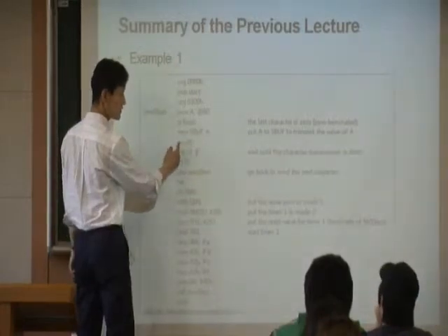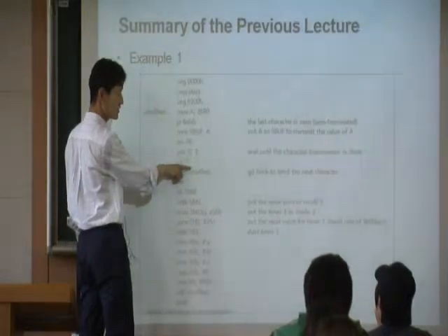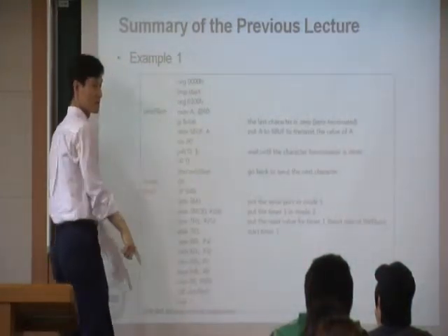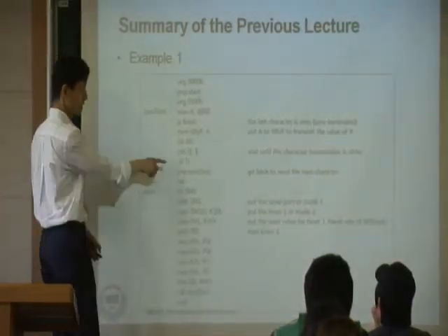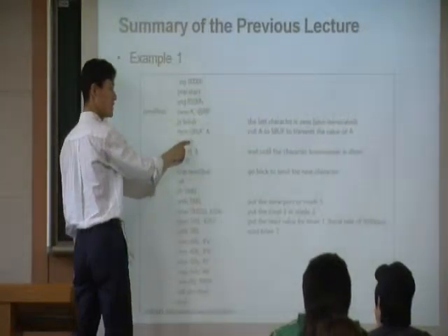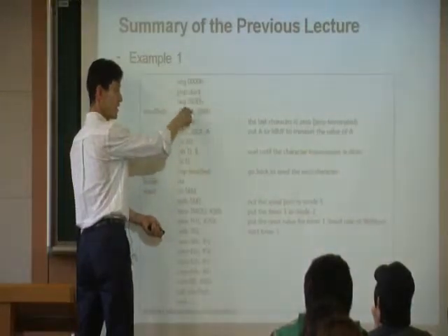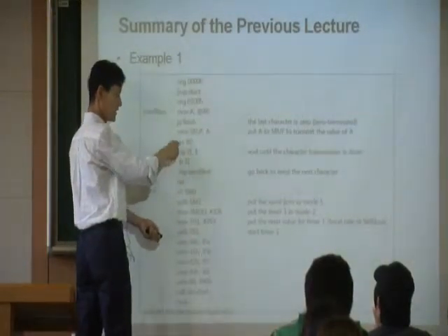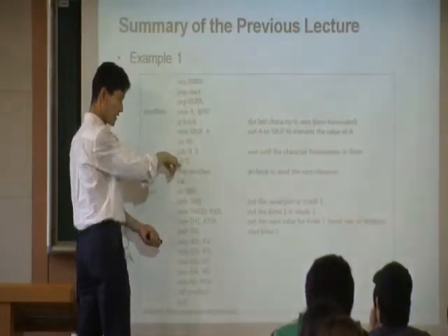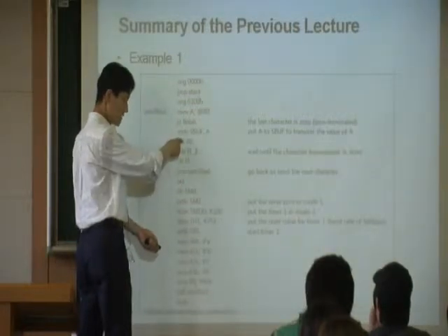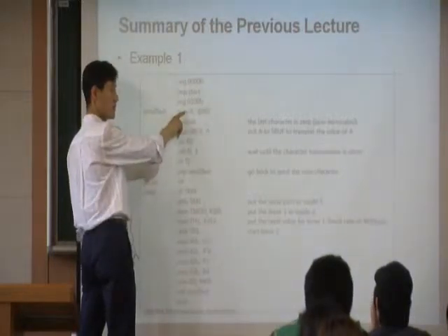This instruction, you can do it here, or you can do it here, it's okay. It doesn't matter, right? But before the jump, you want to do it. So that's what we do. Incrementing R0 and coming back here. Now the R0 becomes 41. So read the 41, which is alphabet B, and you do it again. And increment it again. Now at 42, you read the C. And again, transmit it. Then again, it's incremented. It becomes 43. Now R0 becomes 43, and jump back here.